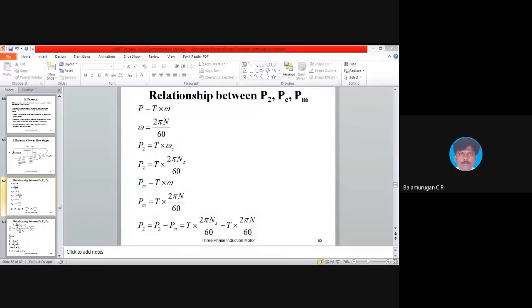Okay? So here you have to explain the vector diagrams of a transformer during no load and load. With load means we have three power factors: unity power factor, lagging and leading. So for no load also you will have a phasor diagram. Okay, phasor or vector diagram is almost the same. So you have to explain the vector diagram. No load means what is the relationship between I naught and the core loss component and magnetizing component, and how you are getting the final current. So you will have the phasor diagram. What is the relationship between voltage and EMF? So all that we discussed. You have to draw the phasor diagram for both the cases. So you have to explain how you are getting that phasor diagram.